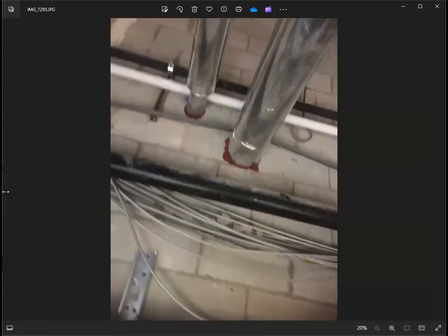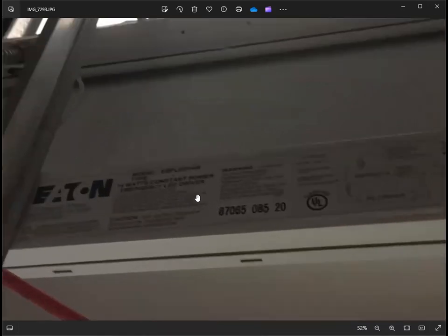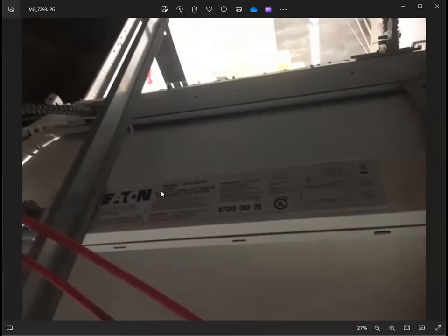And I identified the specs of the light through here. So this is the 14 watts, constant power. There is a light power density that it needs to comply with. So you need to count all the light fixtures, sum the total wattage, and divide it by the total workplace area where the lights are installed.